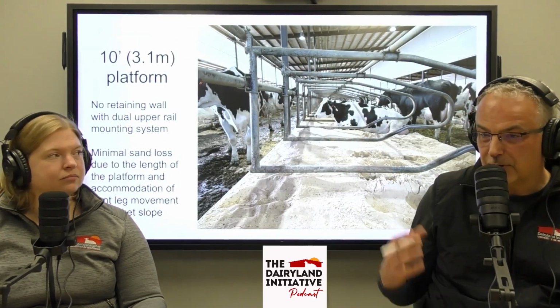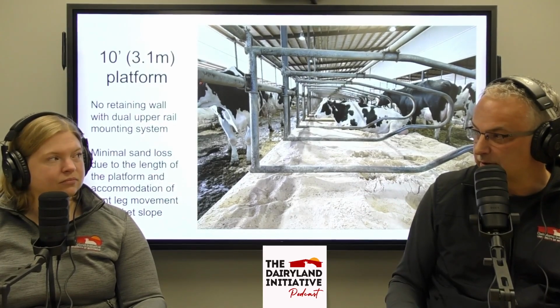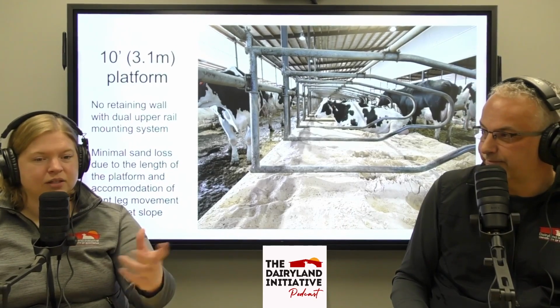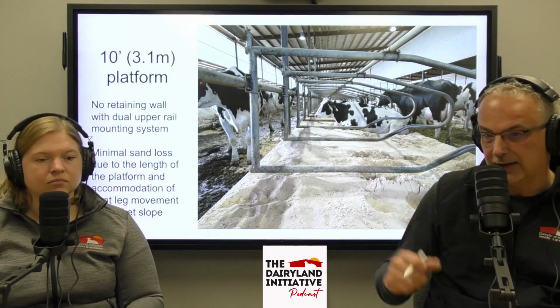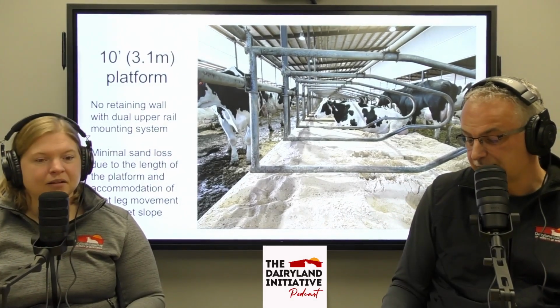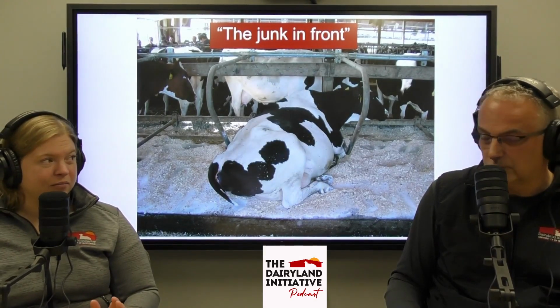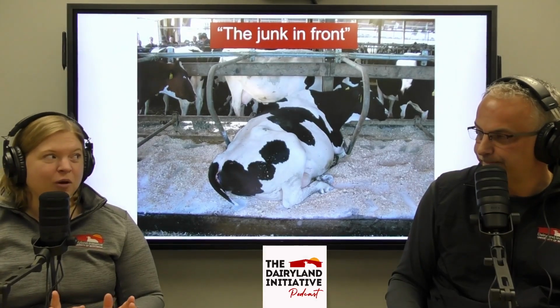This was the most recent one with a 10-foot platform where we didn't even put a retaining lip, because with that 10-foot space, you're not getting a lot of sand getting out the front. With a brisket slope in the front, which we'll talk about in the next episode, you don't lose an awful lot of sand anyway. So that's the recommendation: 10 feet for a single stall platform, wherever it is. For a mature Holstein, we are looking at 10 feet, 3.1 meters long.